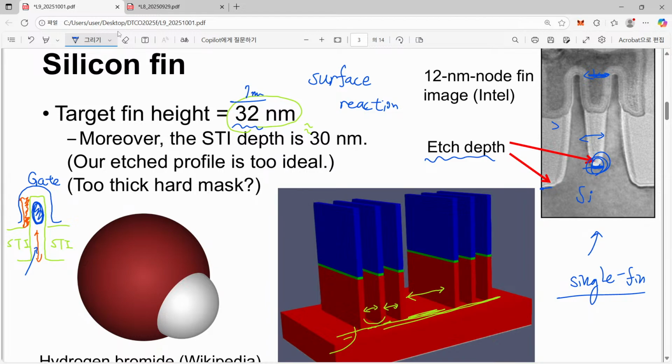Maybe later, when you do your own exercise, you can play with different fin sizes. For example, you could make an even taller fin or an even narrower fin. That can be your possibility to further optimize this system. Obviously, the best thing is a narrow and tall fin.